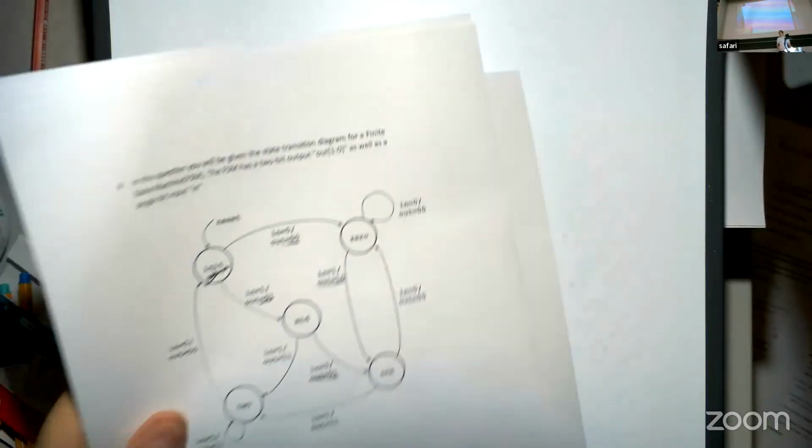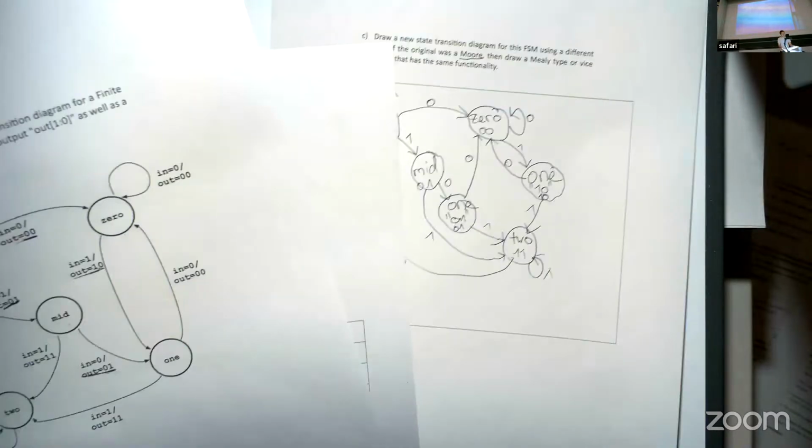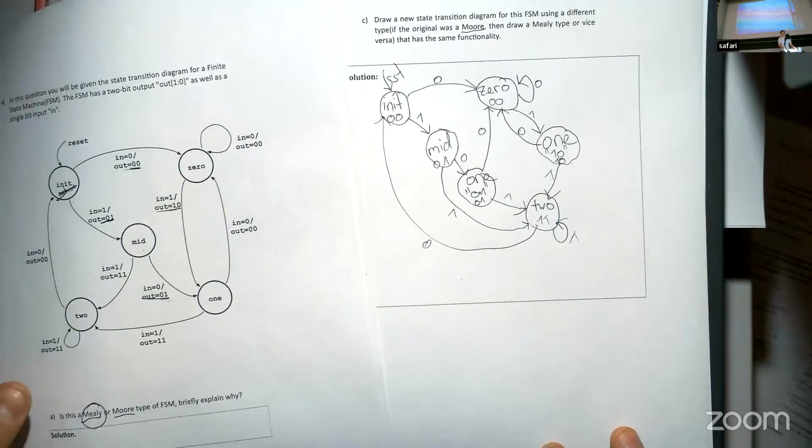Yeah, makes sense if you're programming, I guess. Another question, yes. So this is when we are going from Mealy to Moore, right? And what happens if we go from Moore to Mealy? Here you're allowed to duplicate the states that had two different outputs, in terms of there being two different inputs. If you're going the back way, are we also allowed to merge the two states into one, because we can do it much more efficiently if you're switching from Moore to Mealy?